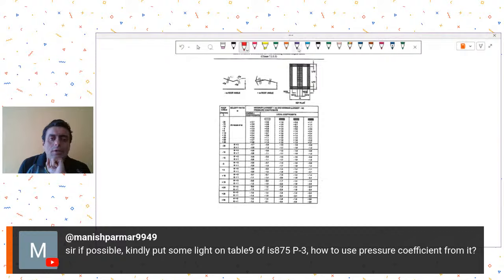And then depending on your roof angle, you can calculate this wind value. So roof angles are given over here. For all values of phi, they have given, and these are the coefficients given to you. Okay. So using this, you could do the calculation. And then they have given you these values also for phi equal to 0 and phi equal to 1. So phi equal to 0 means completely open. In our case, we shall take phi equal to 1.